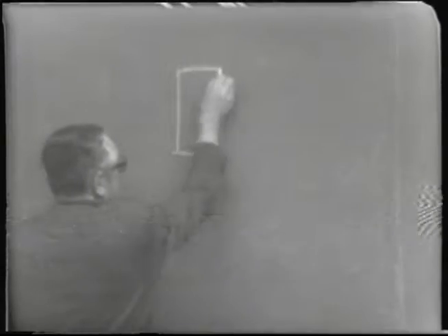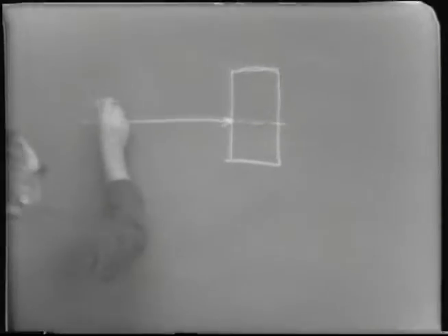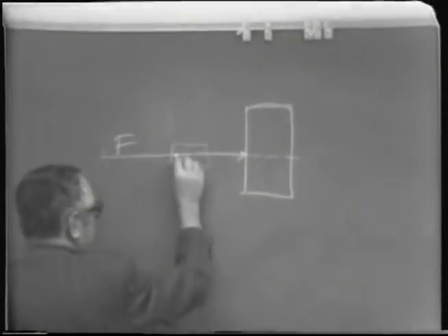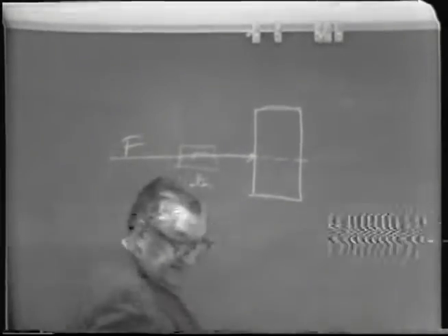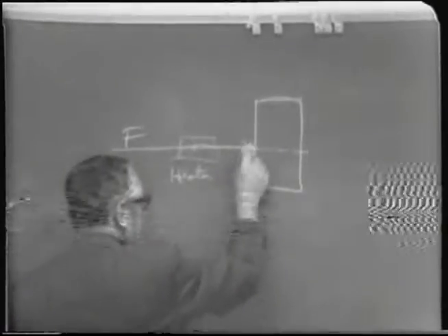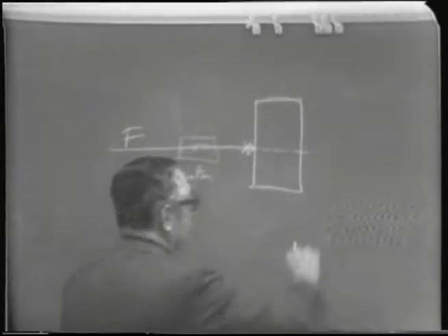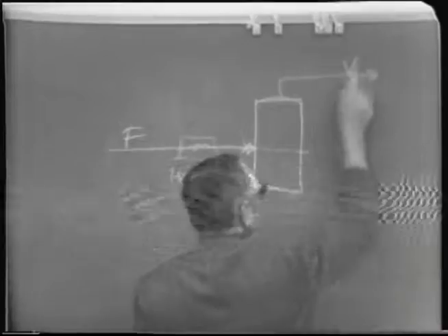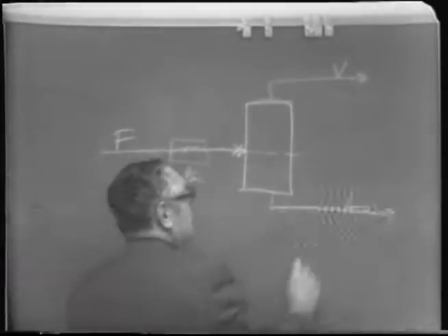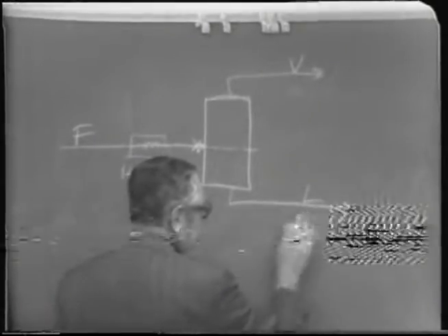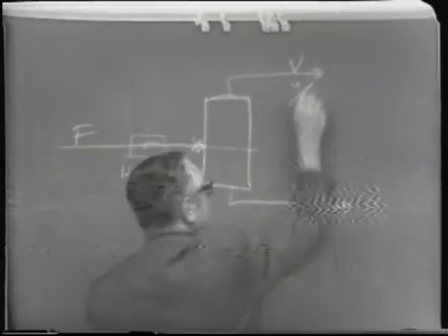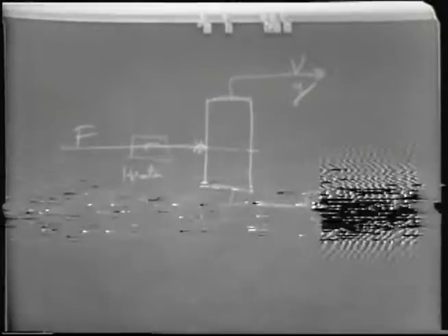If this represents the flash chamber where the vaporization takes place, and we introduce a feed in here, usually through some heater or some device which has increased the energy, and then it either goes through a pressure release valve or maybe under vacuum, reduced pressure, and we separate the liquid into a vapor stream and a liquid stream. And of course, this liquid stream has a composition of X, and the vapor stream has a composition of Y, and that's what we're talking about.